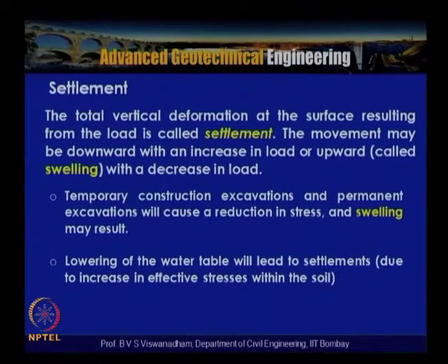The total vertical deformation at the surface resulting from the load is called settlement, and the movement may be downward with an increase in load, or upward with a decrease in load. Excavations, because of the removal of material, cause a reduction in stress and swelling may result. Lowering of the water table will lead to settlements due to an increase in the effective stress within the soil.